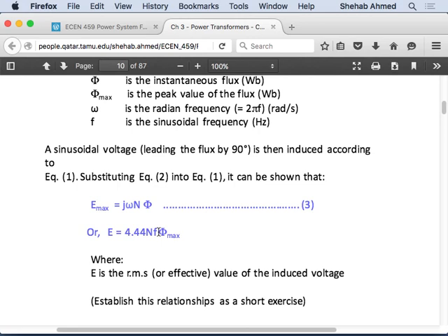This is one of the hypes, and you also get additional advantages when you add power electronics. Let's say you have voltage fluctuations. Then you have power electronics at the input and the output, and power electronics can do anything with voltages and currents. Voltage is dropping, okay, boost it. Voltage is increasing, so step it down. So with power electronics, you also get these additional benefits. You can get improved power quality, and that's what people are proposing.